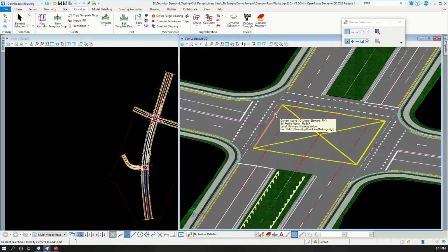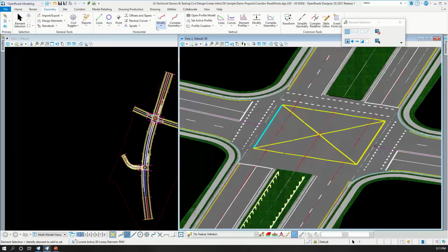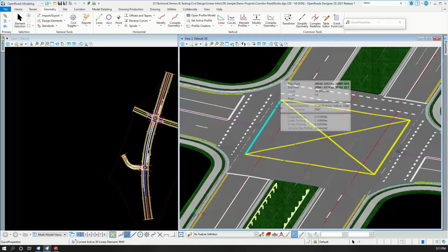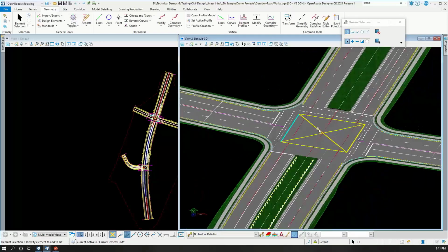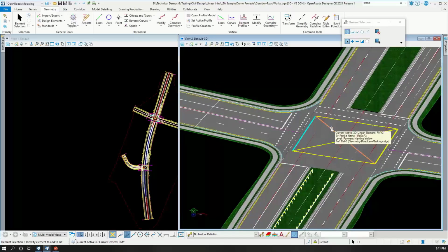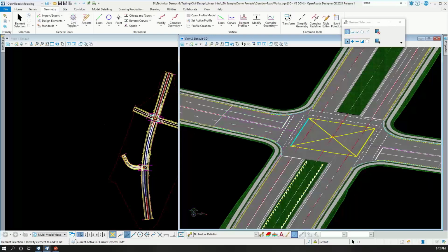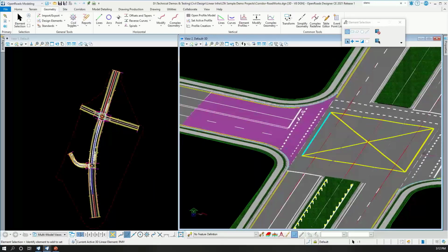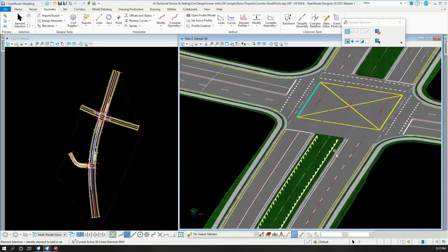Another way, which is basically used here, is using what we call feature definition for the geometries, and then assigning a line style that is referenced by the civil property or feature definition, so that it looks like this already. We would recommend this method because whenever there are changes or updates in the geometry, the pavement markings would update as well, since lane markings should follow the orientation of the road, depending on how it was laid out.